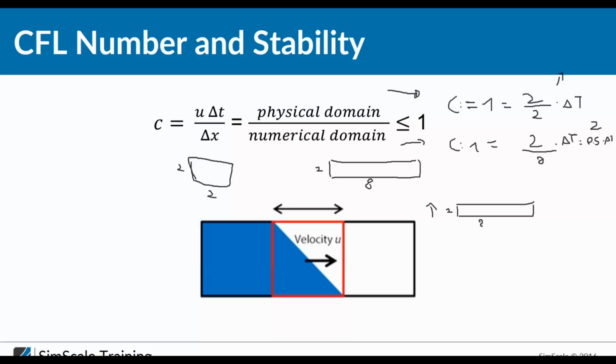But since it's multiphase and transient, the boundary layer is not so important for the total error. So it's possible to have a good result without layers for multiphase, since for multiphase most of the time we have a low Reynolds number. But if you want, I would suggest, let's try it, guys. Just try to add layers and post it into the forum and then we can discuss it together.